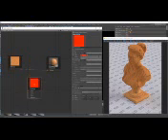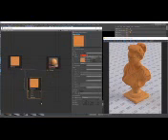You can see the model doesn't have any UVs and it's a total mess. Now let's connect the bitmap to the Corona Triplanar X input. And because in the triplanar the use map X for all axes is enabled, the same map will be used for the Y and Z projections as well. And now connect the triplanar to the diffuse color input.